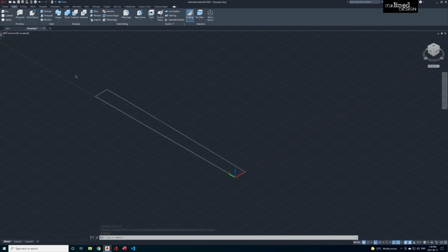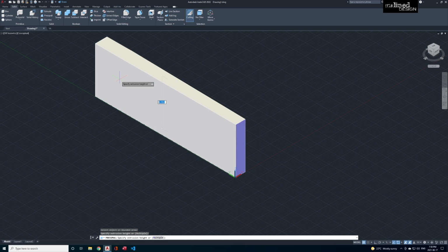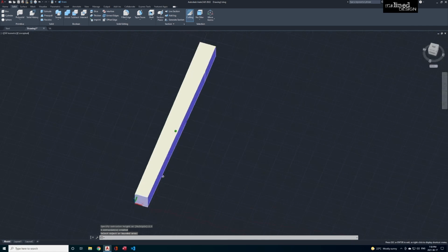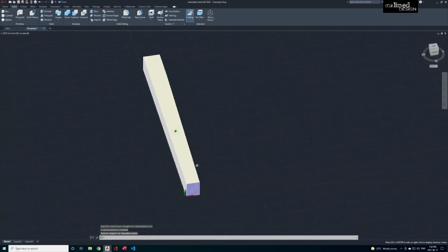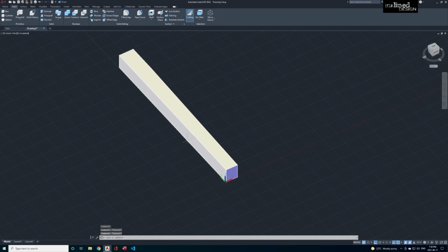I'll show you what I use the intersect tool the most for. So say we've got this leg that's 2.5 by 30, and it's got a taper on the one side. So we just want to extrude by 2.5. The back side is the taper there. I don't know if you can really see it. So you can use the taper faces and enter values.